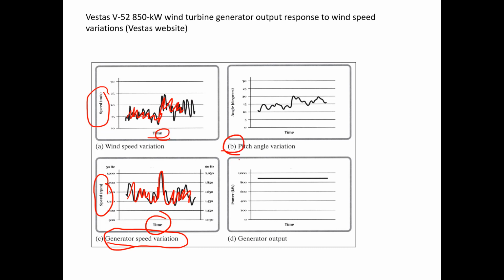So here's the pitch angle, right? The pitch angle, which basically adjusts for these varying wind speeds. You can see the pitch angle, the blades changing over time. The point is to be able to get this. The control strategy is meant to be able to have a constant power extraction, right? So control theory or control application is huge in the area of wind power.